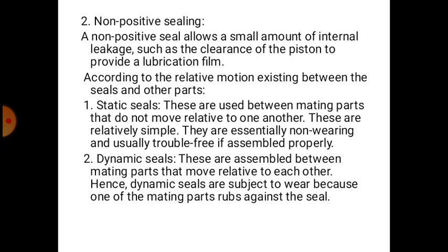Non-positive sealing. A non-positive seal allows a small amount of internal leakage, such as the clearances of the piston, to provide a lubrication film. So it will provide the lubrication film according to the relative motion existing between the seals and other parts.